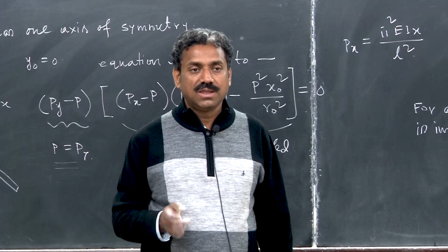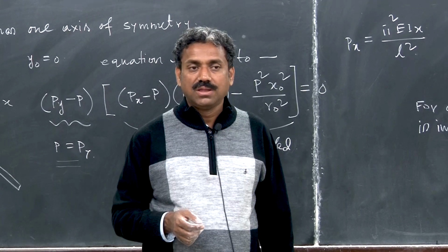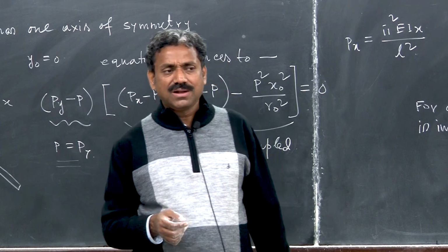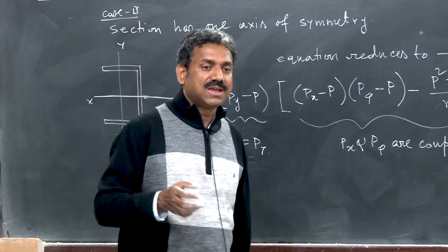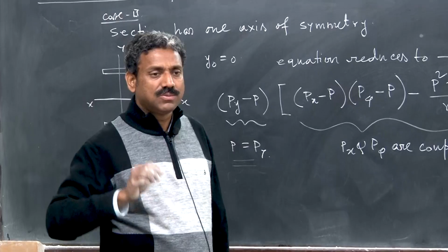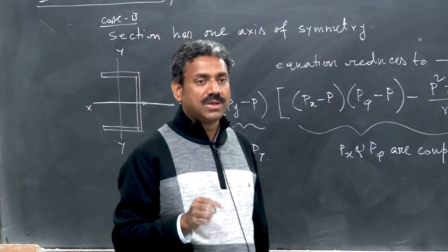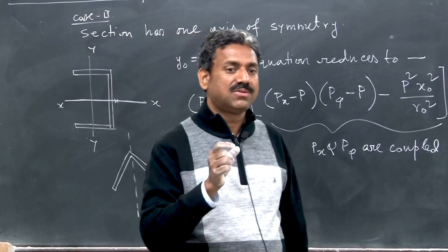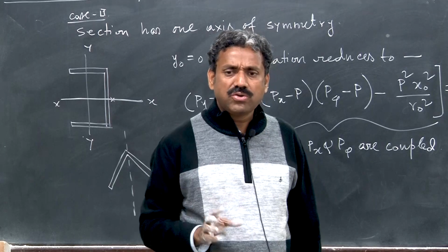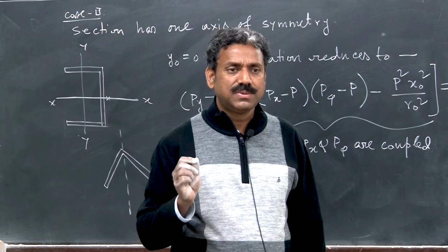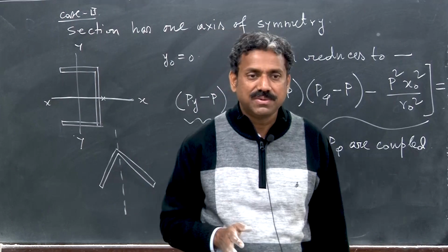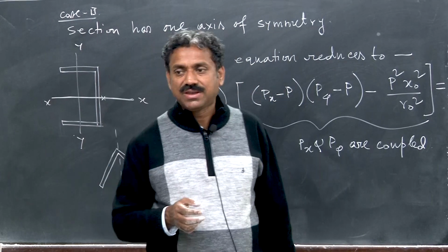You will not see that formulation in other codes. Other codes don't do it that way, but nevertheless they keep a provision for checking against torsional buckling. Other than that, in most cases, the way we connect I sections around the gusset plate, we generally don't check for torsional flexural buckling, because they are symmetric, with either one plane of symmetry or both planes of symmetry.